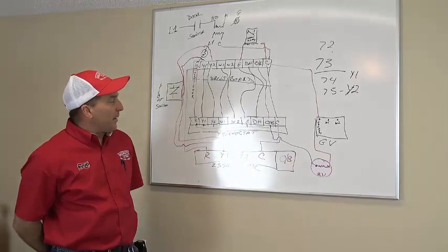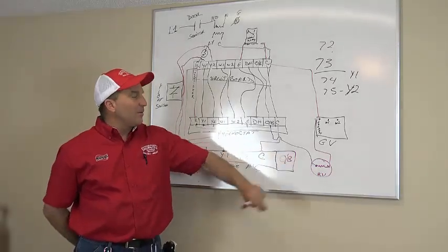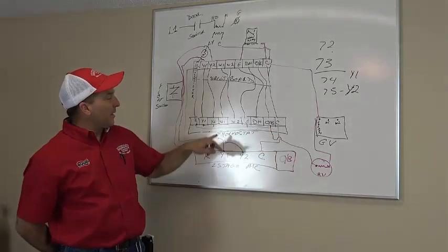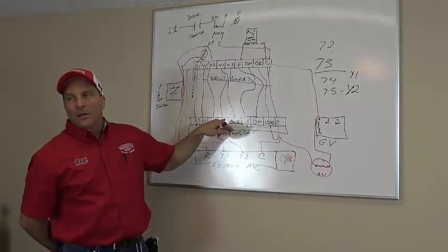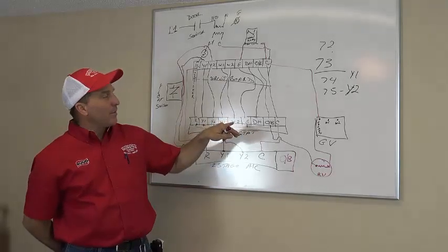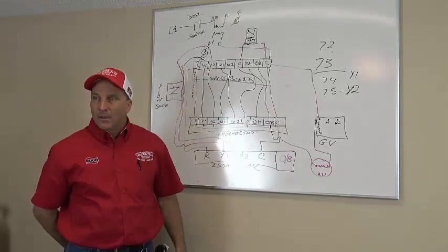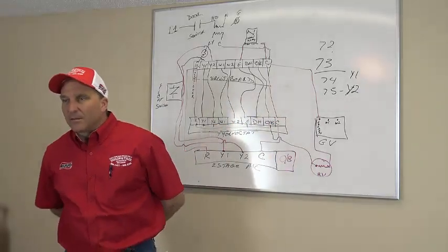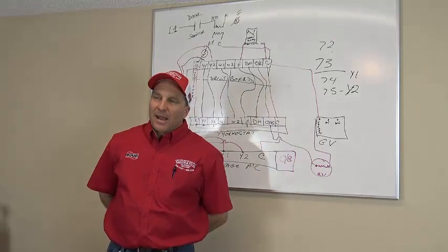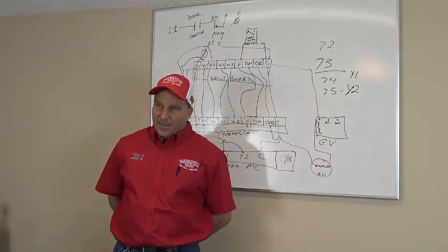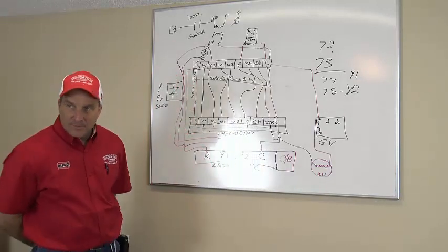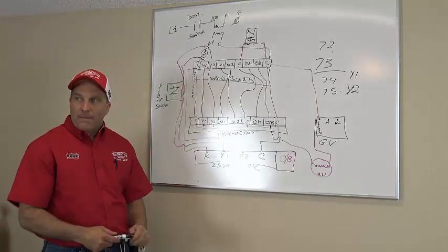So you're telling me I'm going to energize a reversing valve on my condenser, and I'm going to energize the fan motor, and then I'm going to energize my W1, and W1 is going to turn my gas valve on, isn't it? Yes. Okay, that's not heat pump, is it? That's gas heat. Now remember, my gas valve is my second stage heat, not my first stage heat. So what am I going to energize now? You're going to energize W2.